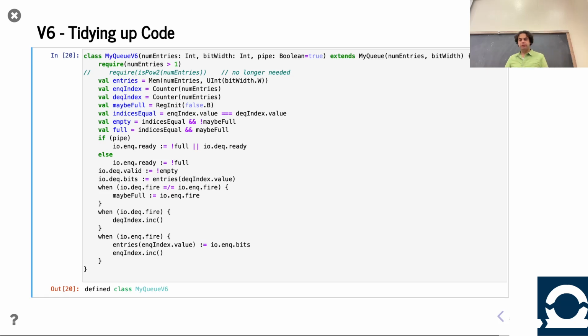So it would be some sort of logic based on recognizing we're empty, right? We're not going to be modifying the counters, because we're not writing to the actual queue. We're bypassing the queue. So you can imagine it'd be some sort of mux here, perhaps, on the DQ bits. It's either the DQ index, or, not or, but mux. In the case we're doing the flow where the queue is empty and someone's enqueuing and dequeuing at the same time. So in other words, if both sides are firing.